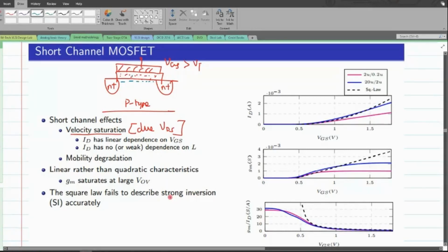I'm going to convey this particular terminology, which we call strong inversion, and we also talk about different other types of inversion that happen. Basically, in order to have a current conduction between the source and the drain, we have to have a potential difference between the source and the drain. When we have this, we end up having current flow from the source terminal towards the drain terminal. So we have this drain current flowing from a higher potential towards the lower potential through this strong inversion region, and this strong inversion happens whenever VGS is greater than VT.